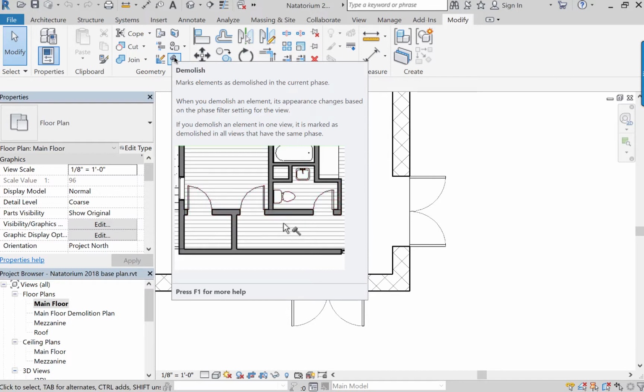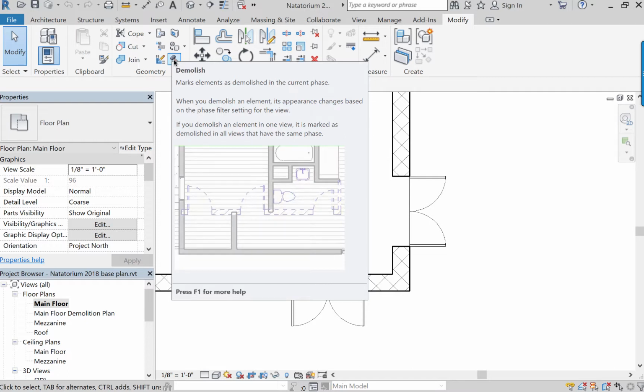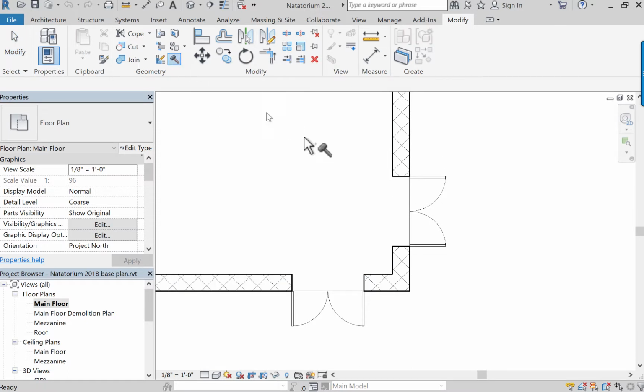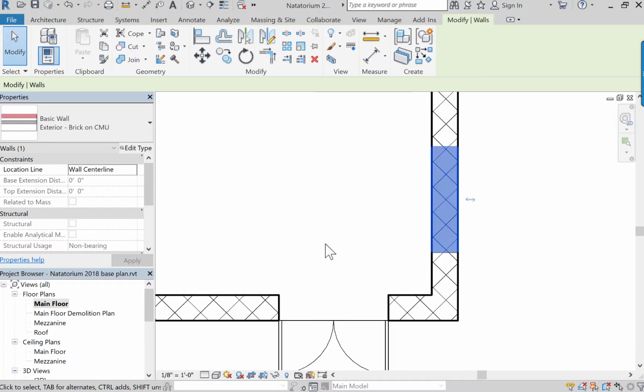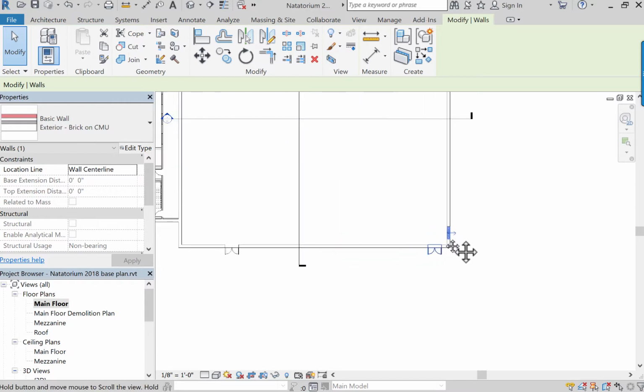And what it does is it takes an element and it changes it to indicate to Revit that something has been demolished. And of course, there's this lovely video going here, which will show you how the tool works. That won't look like it for us. What happens when I demolish this door, I'll click on it, it disappears. And in fact, if I mouse around here, I could probably find that there's a little section of wall that has been filled in. So Revit knows if you take out a door, it needs to fill that opening in. Okay, so that's how you use the Demolish tool.